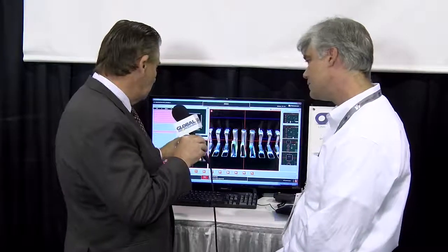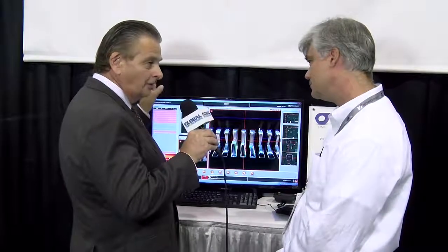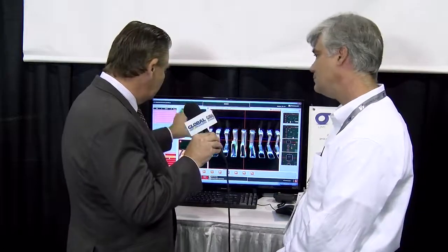Right, they're true metrology tools, as you said. They're measurement-based tools, full volumetric, full 3D for AOI as well, so we have actual data. That's great. I like the idea that if SPI flags a warning, that warning will come up again at AOI, so you get a double check to verify that it did actually pass correctly.